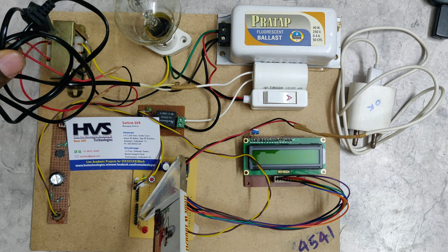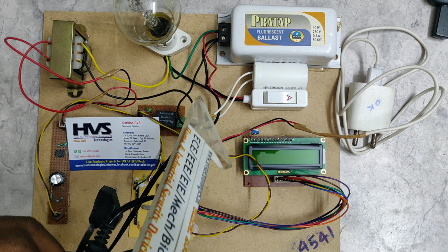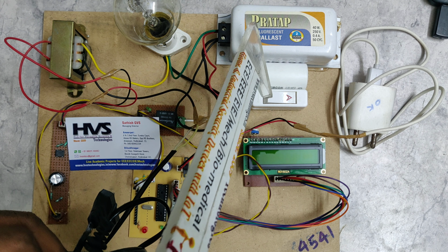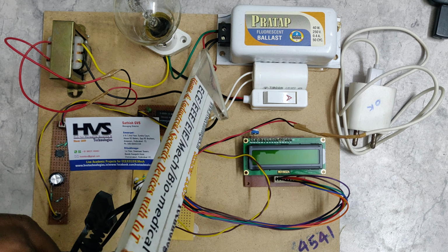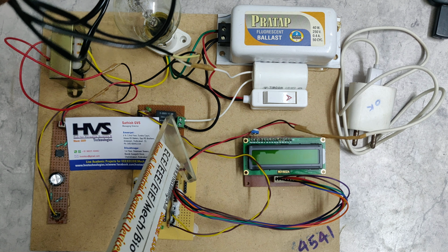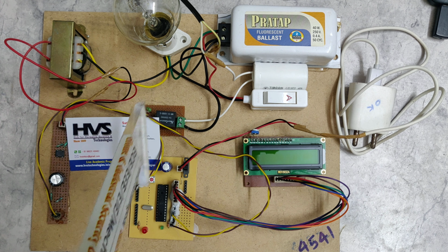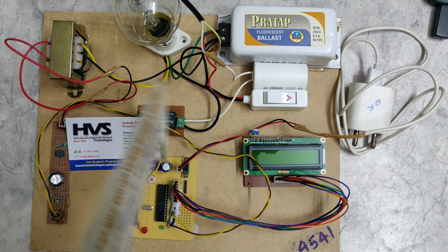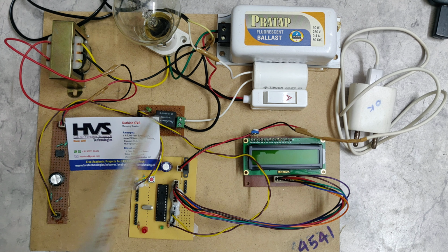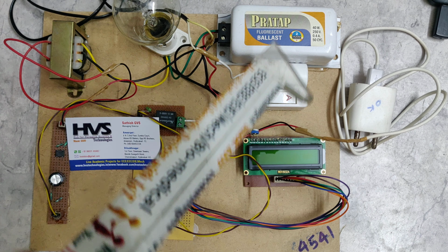This is the transmission line, and we connected a bulb and an inductor in series. These two loads, R plus L, are in parallel with the capacitor and the relay switch. So this is the main connection. Here is the CT, and we check the current waveform and the voltage waveform from this PT. This section is the controlling and monitoring part, and this other section is the transmission line part.